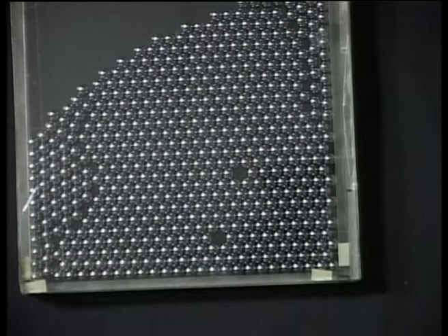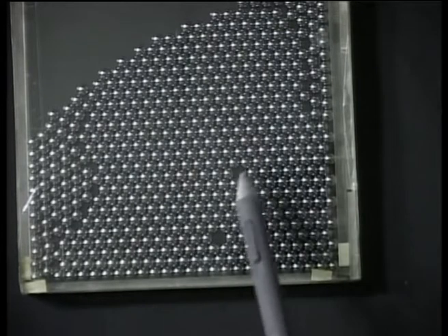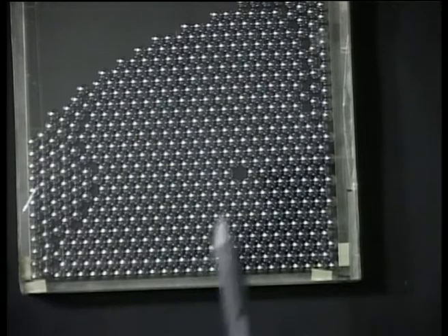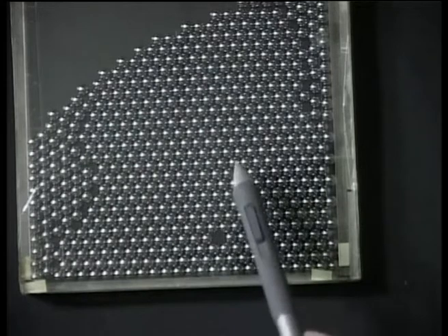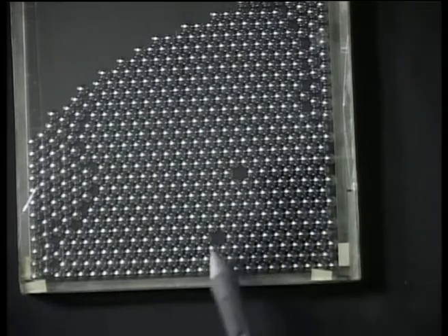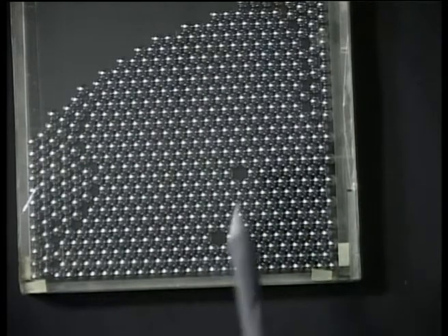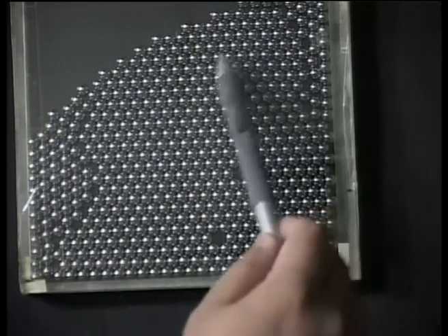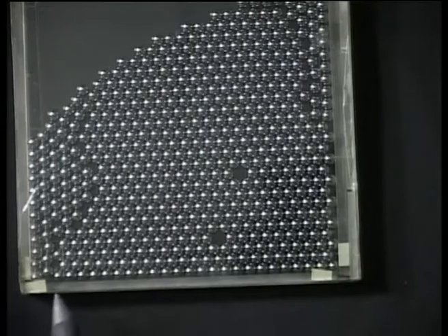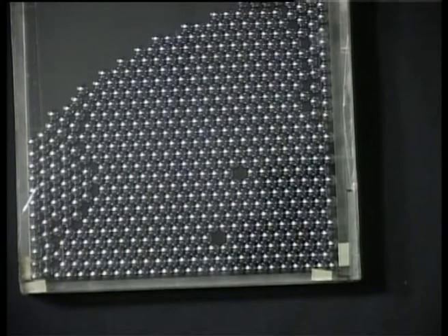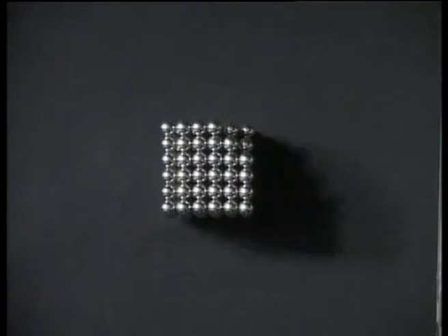Of course, this is just a toy model, but still you can see that these vacancies are difficult to shake away and they persist, and this is taking analogy from our understanding of vacancies. These are like our equilibrium concentration of vacancies. So we can see that a small toy model like this, which just consists of some spherical metal balls between 2 perspex sheets, can actually give you a nice picture of what a crystalline array is and the concept of grain boundaries, etc.